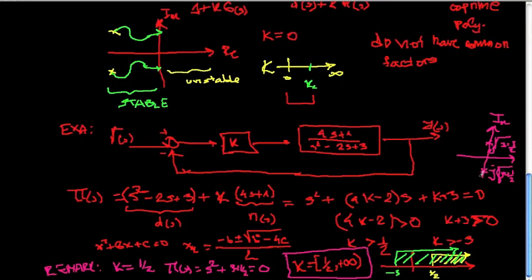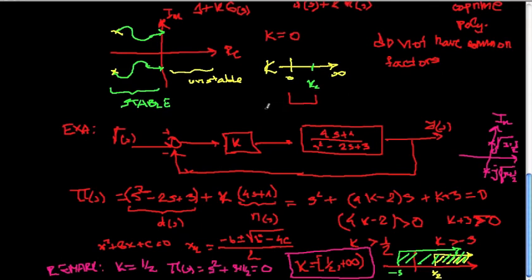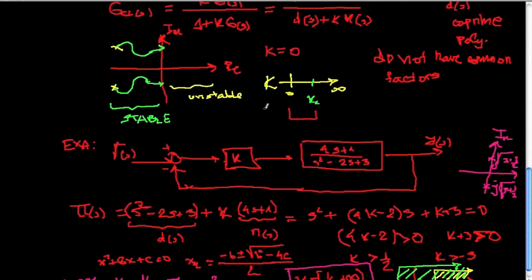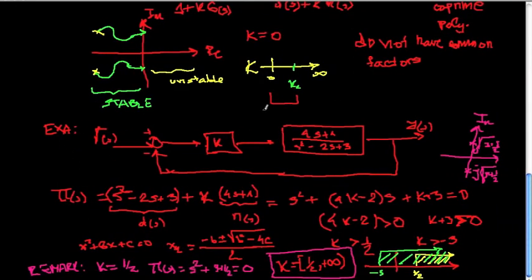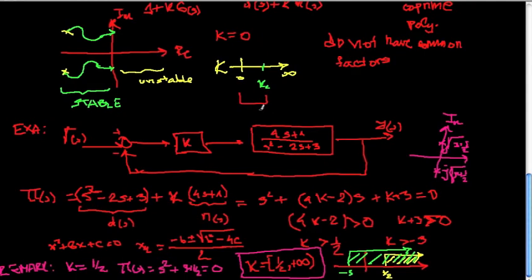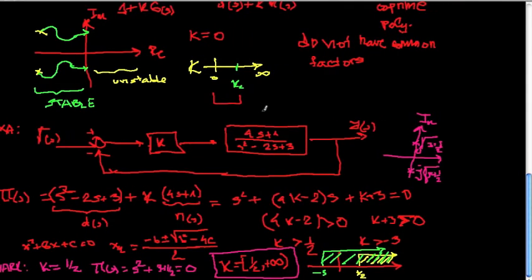This is the moment where the gain will shift the closed loop characteristic polynomial poles from stable into the unstable limit. Okay, we see that the regulator synthesis with a simple gain is very easily done, and it can be easily calculated if there is a stabilizing gain. Okay, we will also demonstrate another synthesis where we design dynamical control, and that is the case when K cannot stabilize the closed loop system.